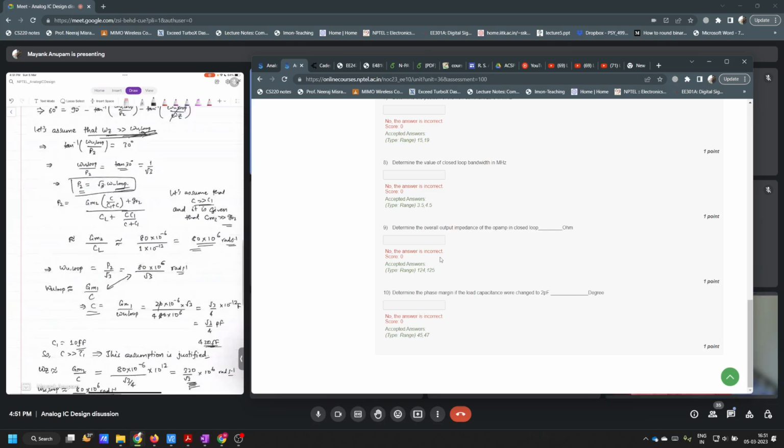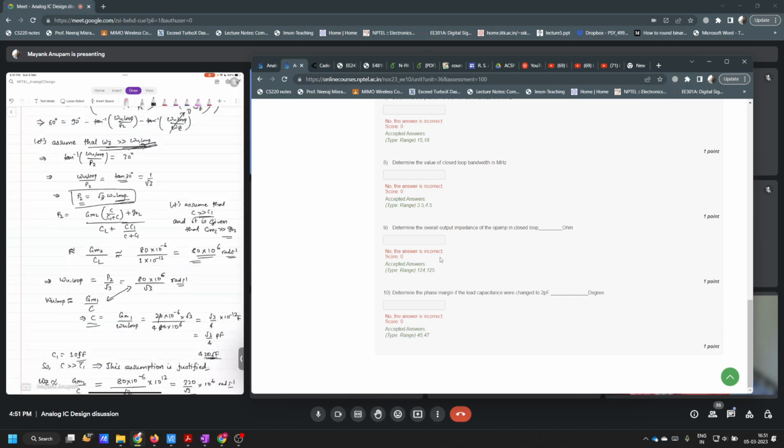But still, sir, for those approximations we use c much greater than c1. Up to how much? If the value is greater than 10, it's okay. I mean, 10 times is good enough. So something like 10 and 200, I can approximate it as 200 only? Yes. If you take a factor of 10, that gives more or less an error of 10%, which is generally tolerable.